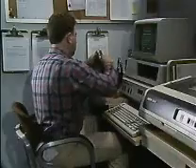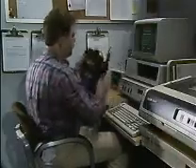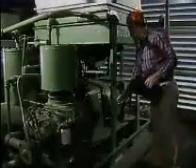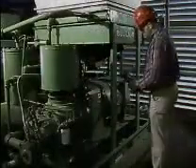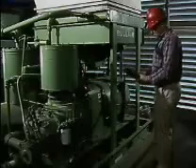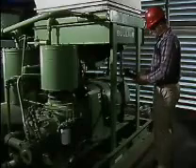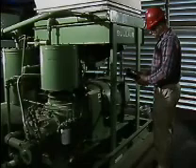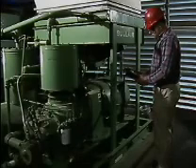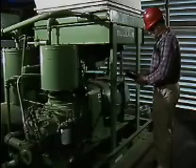The data collector is then disconnected from the computer and taken to the first machine from which data will be collected. Usually, an overall reading of vibration velocity is taken first. An overall reading of vibration velocity is generally taken first to determine the general mechanical operating condition of the machine being tested. Specific frequencies and different vibration characteristics can then be measured if required.